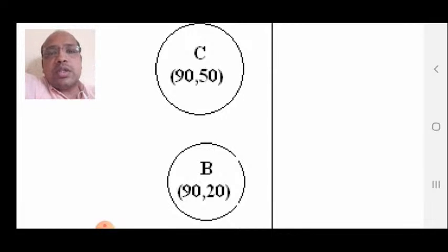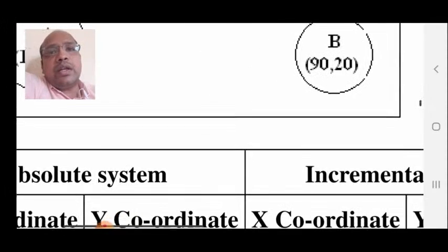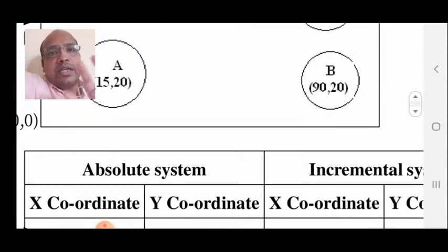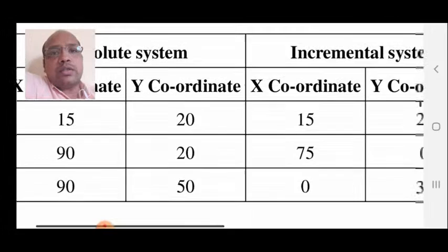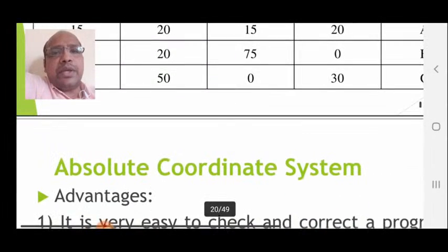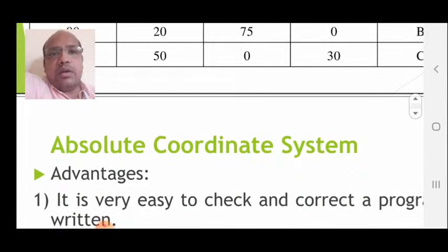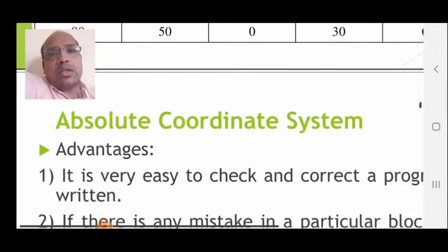So it is quite risky to write a part program in the incremental coordinate system. The better way is to write a part program using the absolute coordinate system.